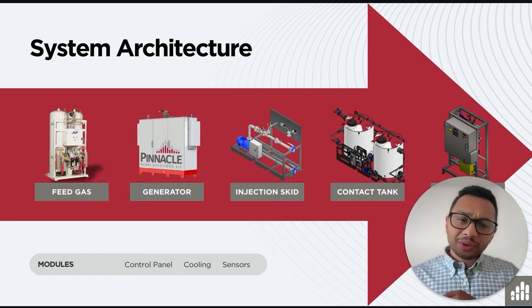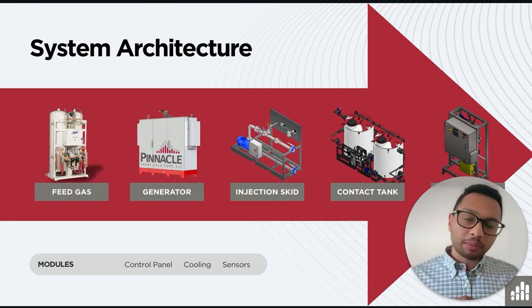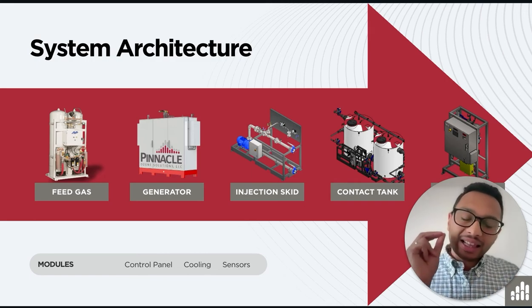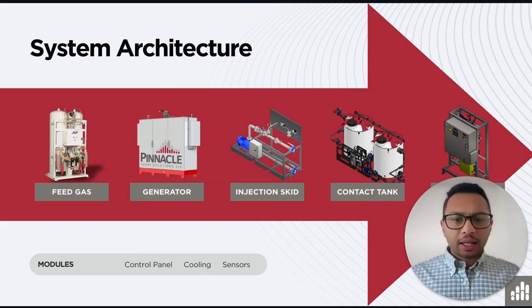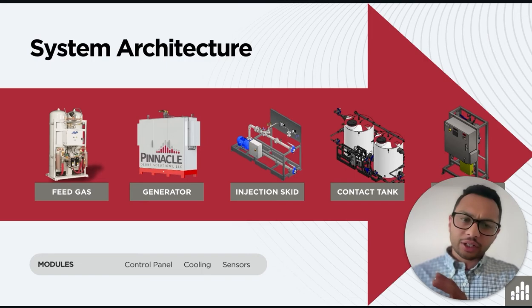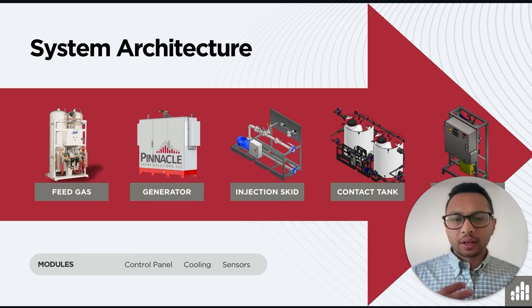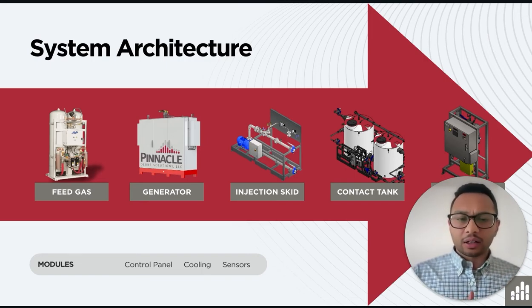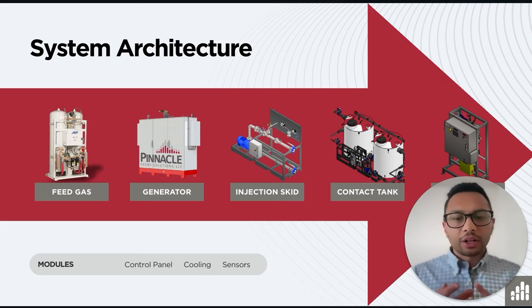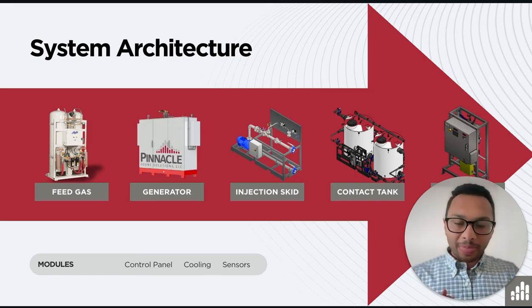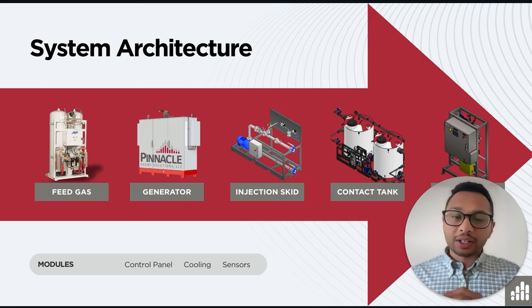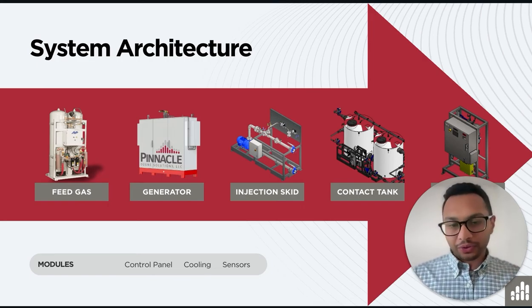Getting as much ozone into the solution is the most important, and also getting it there quickly is important. Once the ozone is into the water, it enters a contact chamber. This is where oxidation and disinfection actually occur. Designing here is critical. You need the right CT value, the right retention time, and you need to make sure that you're actually getting the ozone into the water. If you take a shortcut during this step, you will lose the power of ozone.